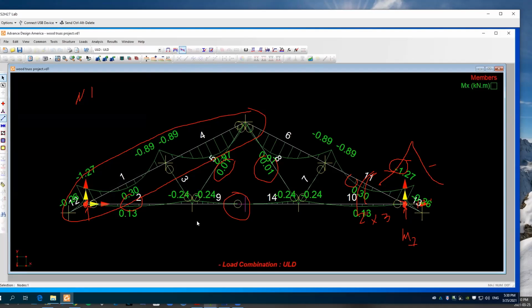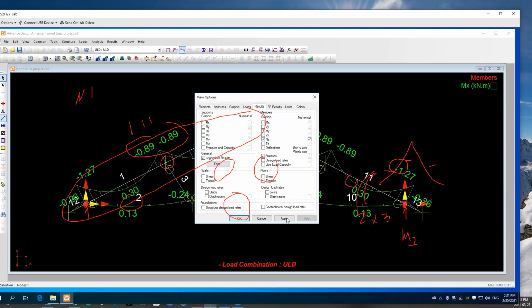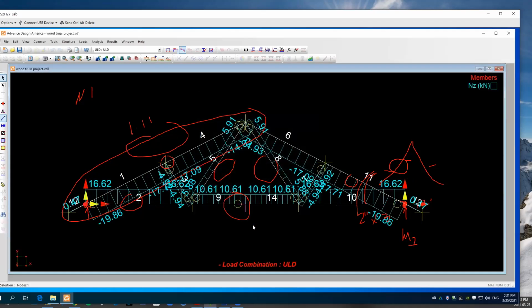But look at the difference now in the bending moment. Right there, and look at even the one right here. Remember, this was 1.11. And if you go look at the axial forces, just for the hell of it, it's even reduced. You understand? It changed the axial force. So just this one little support helps you to redistribute a lot of your moments and stuff.